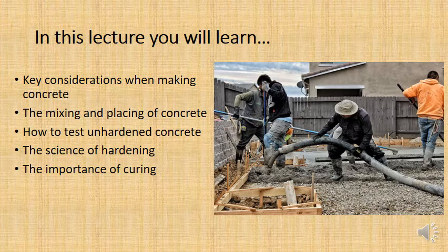Now, hardening is not what you think. I touched on this when we did cement together. Hardening is not it going from being a sludge to solid. It's a case of it going from being weak to strong. Concrete, even after it's dried and it's gone solid, the chemical reaction of cement turning into strong chemical bonds will go on for many days and months, and I'll show you that later in a graph.